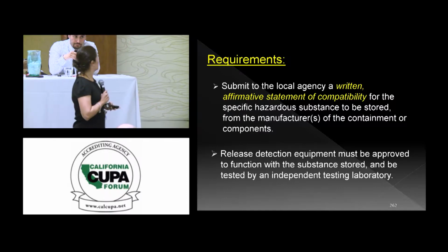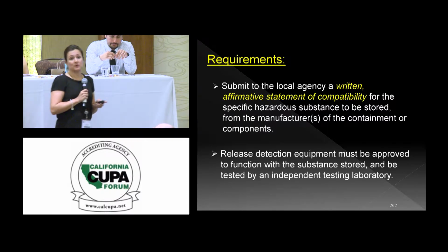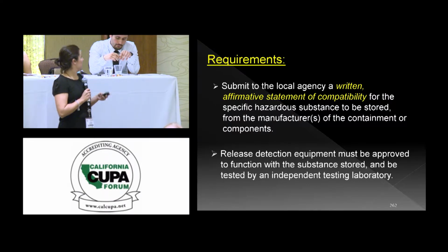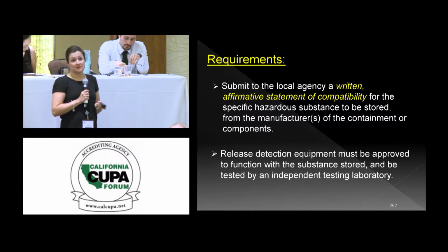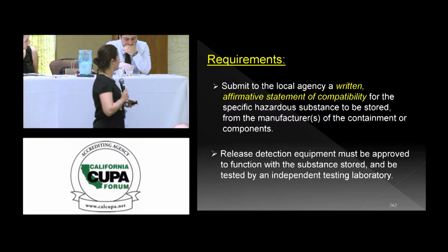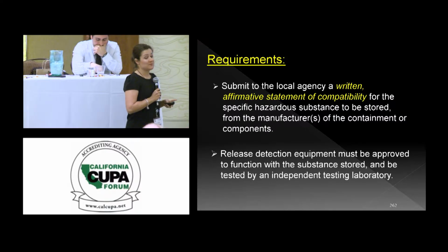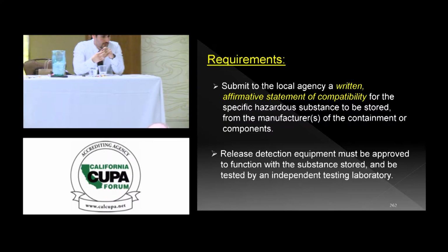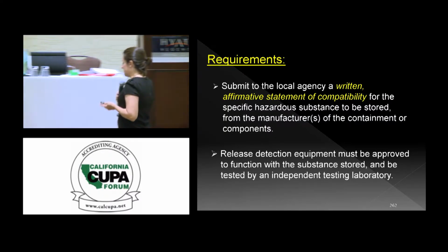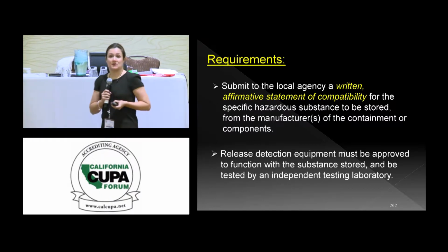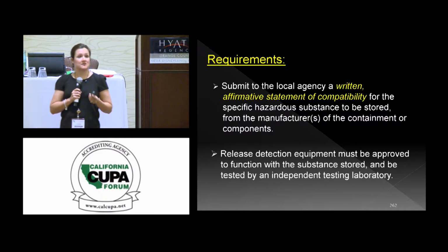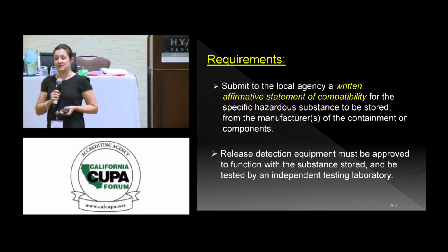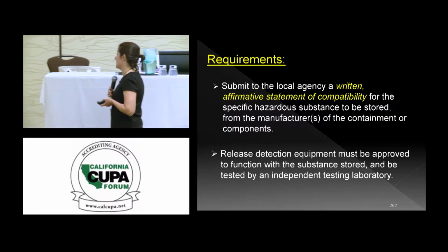Okay, so requirements. If this is something you'd like to add to your lineup of fuel, we're going to need a written affirmative statement of compatibility. That's going to your local CUPA, and it's going to give you details on the specific hazard that's going to be stored. The important thing is to get these documents from the manufacturers, because right now they're the ones telling us that this is something that can be used in a UST tank system without any detrimental effects.